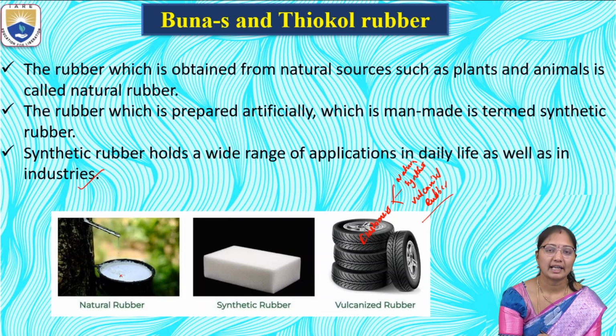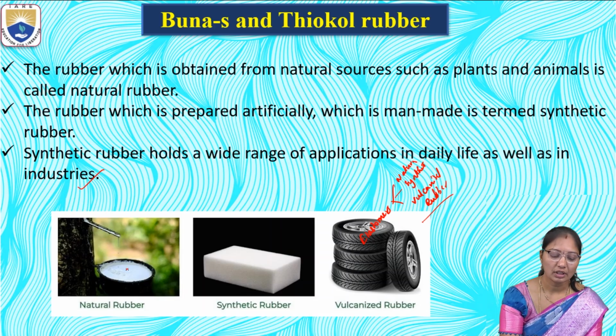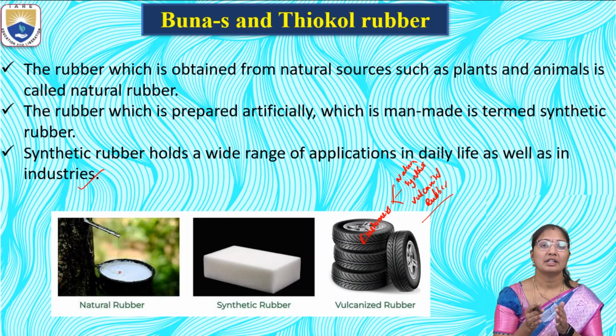This is called natural rubber. After being collected, it undergoes a series of preparation methods to be converted into rubber sheets. A preservative, generally ammonia, is added to avoid traces of cations like calcium and magnesium. It is preserved and strained, and goes through a series of reactions to convert into rubber.